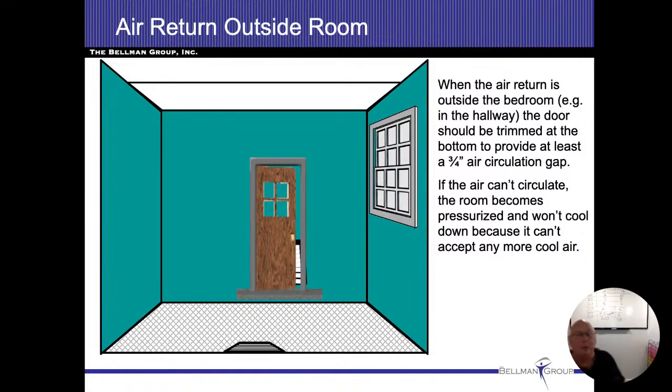All right. Typically, if they're going to use the bottom of the door, we should have about 3/4 of an inch on the underside. Me personally, I like it when they put those vents up over the door, or at least on the side of it, so they let the air flow through that way. I know that doesn't help much with sound, mind you, but if you don't let the air out of the room, then we can't let more air into the room.